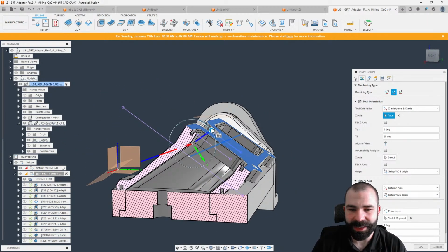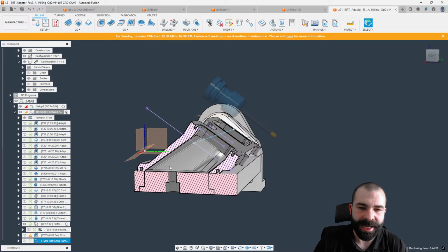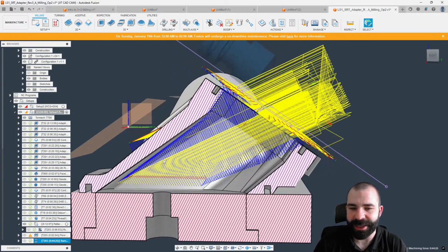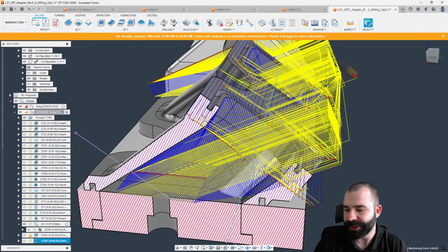And then what I'm going to do is hit F7, which turns off that toolpath. So again, what I'm doing is tilting my Z back more to see if I can get up under there. We're going to see if that changes the angle of that blue line. Does it give me more reach inside my part? What is going to be limited now with what we're doing? I do need to hit F7. Again, what we're seeing is we are now getting up underneath there. Obviously, we're getting limited as well down here in this area.